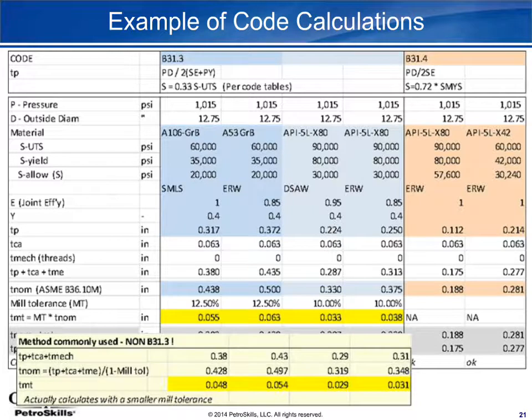304L is usually a requirement for welding on stainless steel. When they manufacture stainless steel piping, and this steps into metallurgy, which is perhaps not my strong point and probably a subject for another webinar entirely, but generally speaking, if you're welding stainless steel pipe together, then when you weld the carbon on a regular carbon content stainless steel, the carbon will react with the chromium in a process called sensitization and reduce the corrosion resistance of that stainless steel piping.